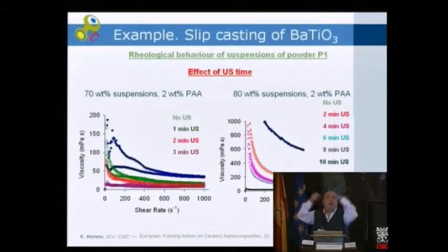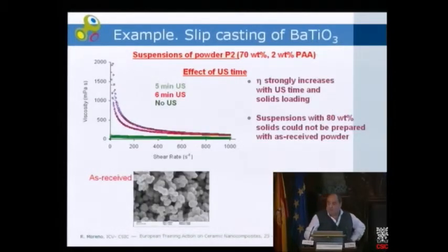First of all, we need to optimize all the colloidal stability and so on, as I have done before, and I plot here the rheological behavior of concentrated suspensions. These are suspensions of 78% with polyacrylate. And we see that the viscosity decreases as the ultrasound mixing time increases. And we are able even to reach suspensions with 88% solids that can be cast into a plaster mold.